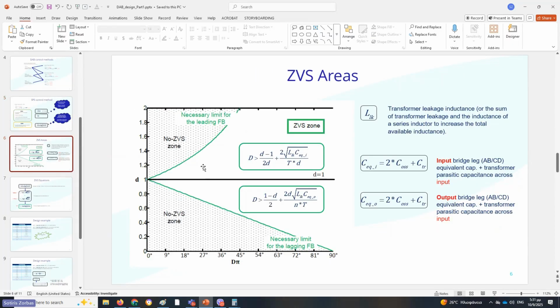It should be the high voltage case. Why? Because at 54 volts it will be a partial load, a low load condition, so we are approaching the zero voltage switching limits.